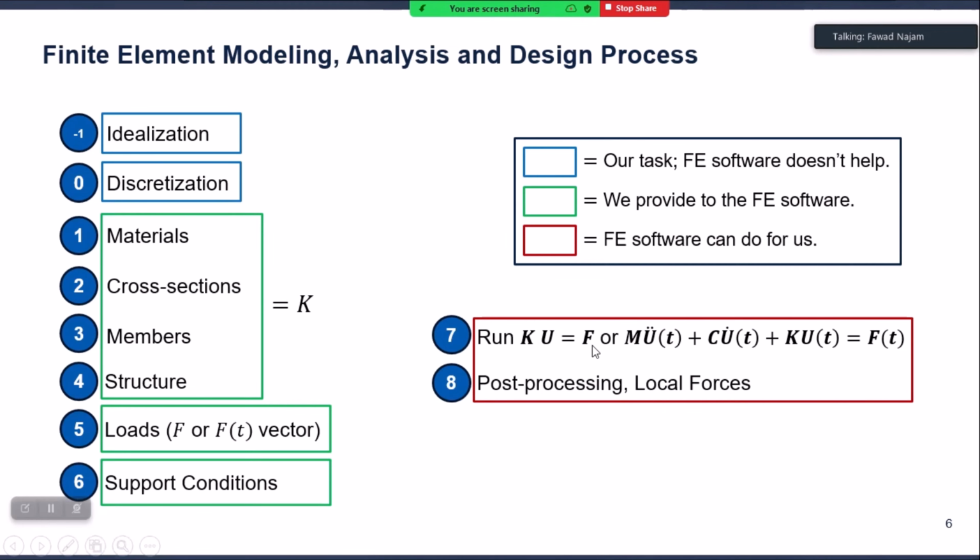It will solve F is equal to Ku, the detailed matrix equation of motion for your full structure, if it is a static analysis, or this complete equation of motion, the inertial force plus damping plus static elastic restoring force is equal to the dynamic force, if the analysis is dynamic.